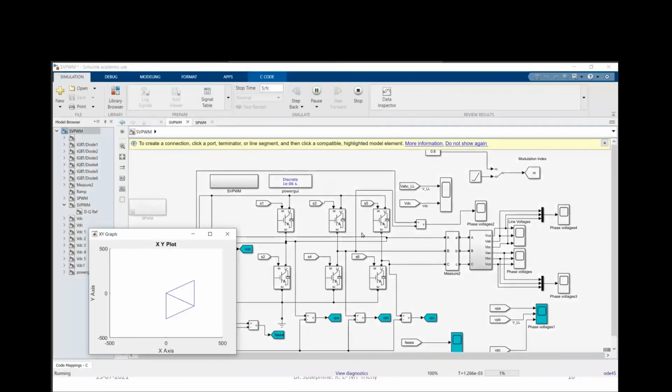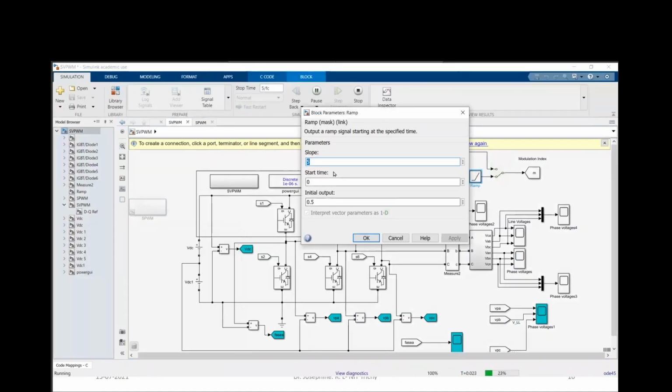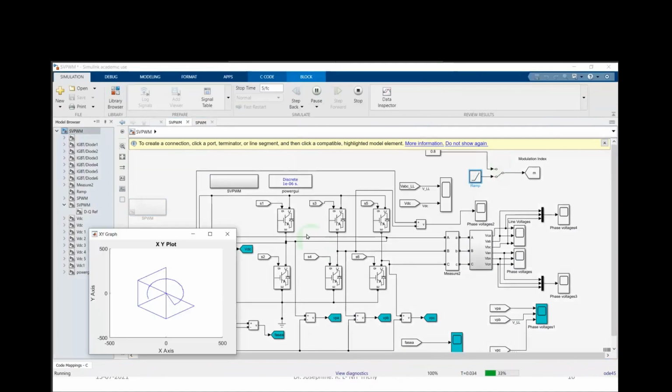So you can actually see that vector that I have identified. In that vector, it is going to move, as here in the modulation index, I'm varying from 0 to 5, somewhat randomly. So what does it do? It actually moves. That means I'm slowly increasing the modulation index, which means I'm increasing the sinusoidal reference. You can actually see that it is going to move from higher value to higher value like this.